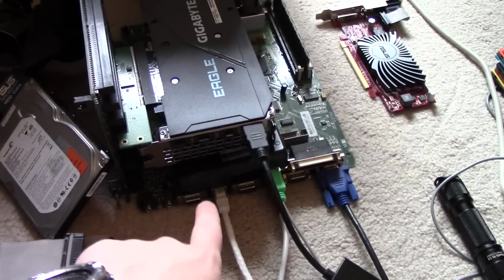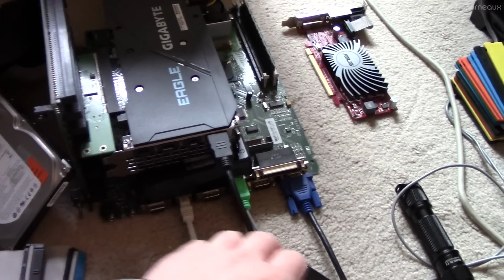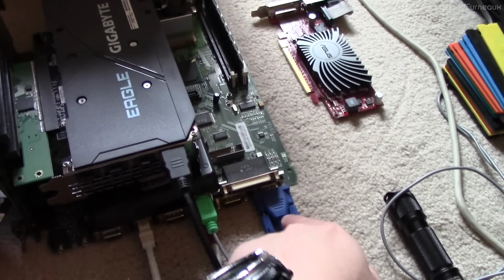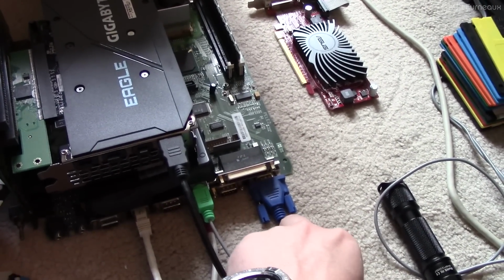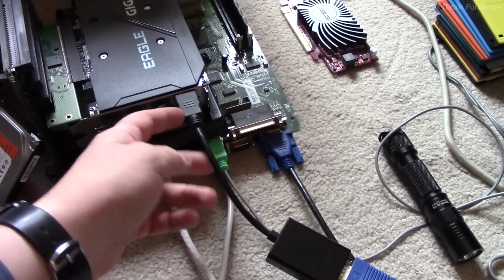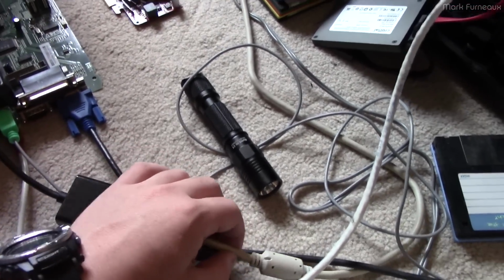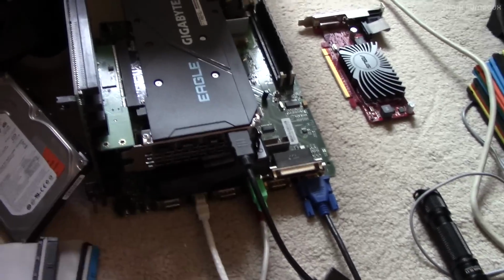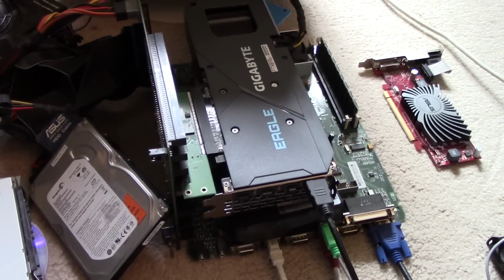The weird firmware on this motherboard, because of course it's an ATM, requires something to be plugged in here so that it can get an EDID. It will not post without this, but once it posts, I can even unplug this and it will make no difference. So to prove to you, obviously this is coming out through here, going through the cable that's attached to the actual CRT, and it goes back off there. So we are actually driving out of this, and there's no power button on this.